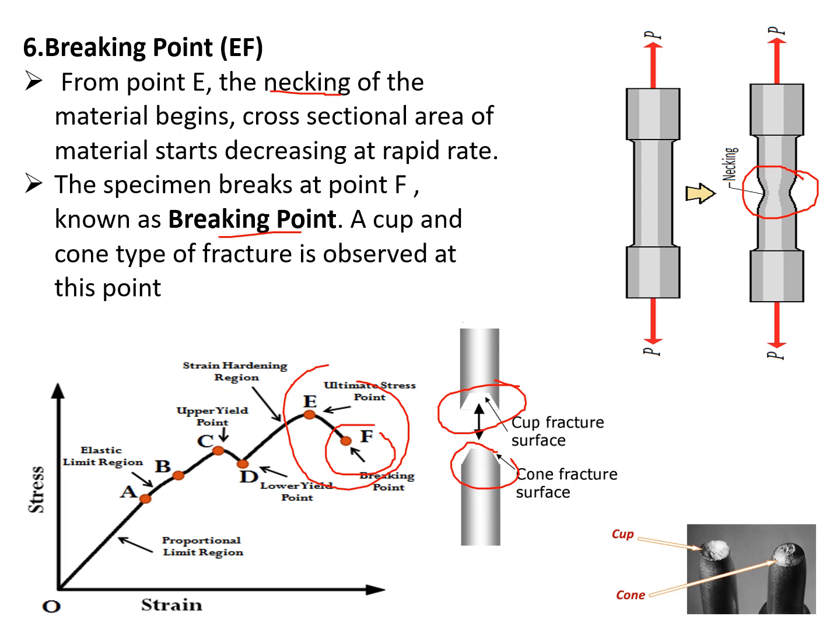And this is about the stress strain diagram. And also I will tell you the stress which we are plotting here, that is the engineering stress, because that stress is the force divided by the original cross-section area. So here at every point of the stress we are considering the initial area of that specimen, so that is known as the engineering stress. And the other stress, that is known as the true stress, in that we are taking the instantaneous area. So that is the difference between the engineering stress and the true stress.